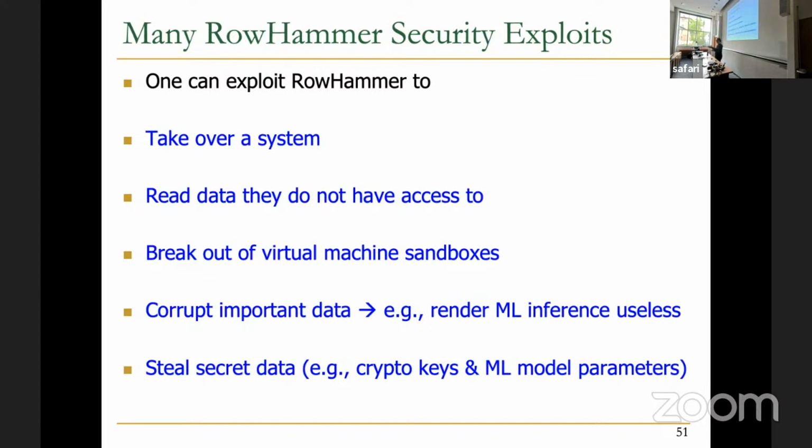Yeah. Okay. Yes. What about stealing? Like, how do you steal the row? Would you attack what you didn't really access? Okay, let's leave that to next week. But the basic idea is that you can read data that you don't have access to. RowHammer has this property of data pattern dependence. Some data patterns are much more vulnerable to RowHammer, and you can guess what data is stored in a nearby row by actually causing RowHammer not on that row, but on the row next to it. This is called RAMBleed. It's a paper, and they basically have this attack. I think next week we'll discuss these more, and you can have more detailed questions.